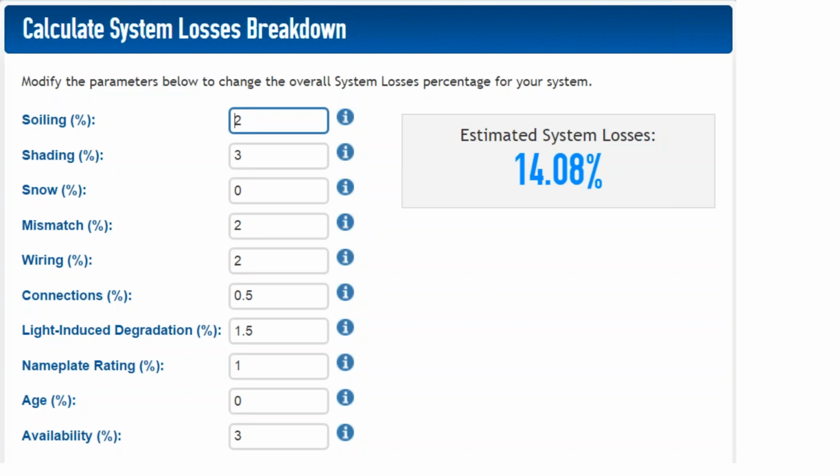And so that means for your performance estimate, you may need to clear off the month of January if you know that there's going to be snow on the roof every year and your client is not going to do anything to clear the snow off themselves. And so that's one pitfall.